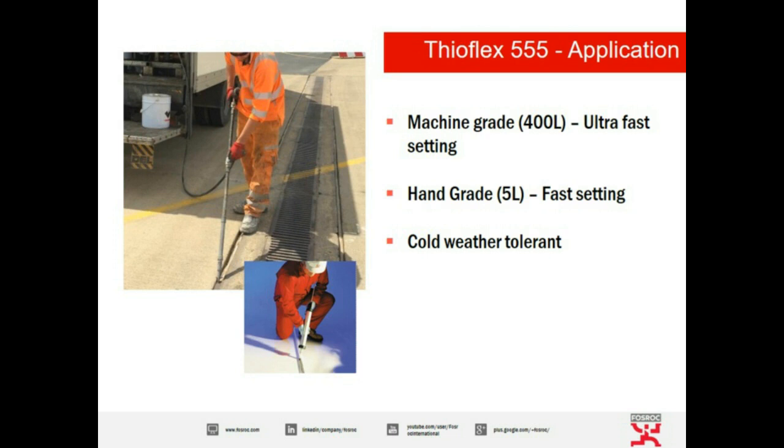So you can imagine the efficiency you can get through on this product in realistic European temperatures and further afield as well. At 5 degrees, you will have that fully cured, ready for service, not just touch, not just gel time, but actually ready to be put back into full operation, be that on an airport or wherever it is, within 90 minutes at 5 degrees, and 20 degrees would give you just half an hour.